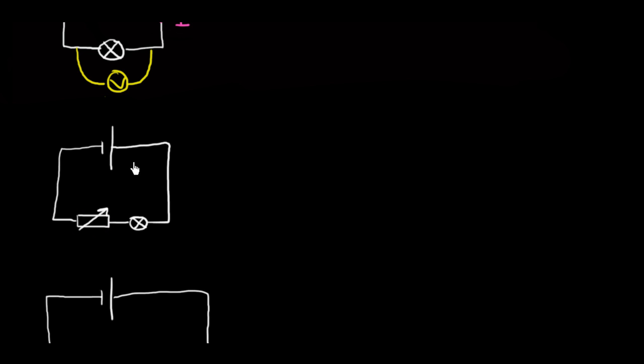And the idea there was to understand how the EMF is then as a potential difference in the circuit, how it's then divided, how the division of it changes depending on the resistance of each particular component. So we put a voltmeter through both of them, both components. So I'm going to include here 1 voltmeter across a variable resistor, and we put another voltmeter across this light bulb.